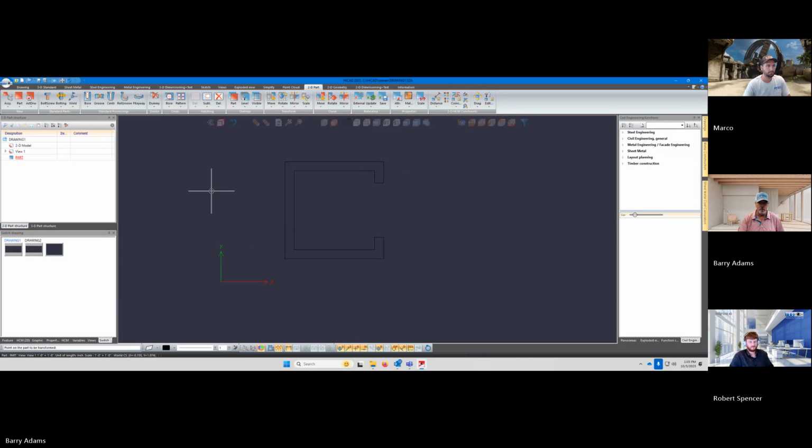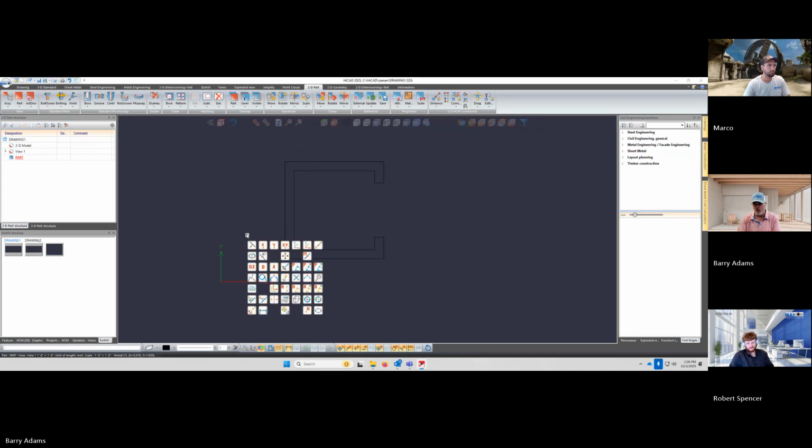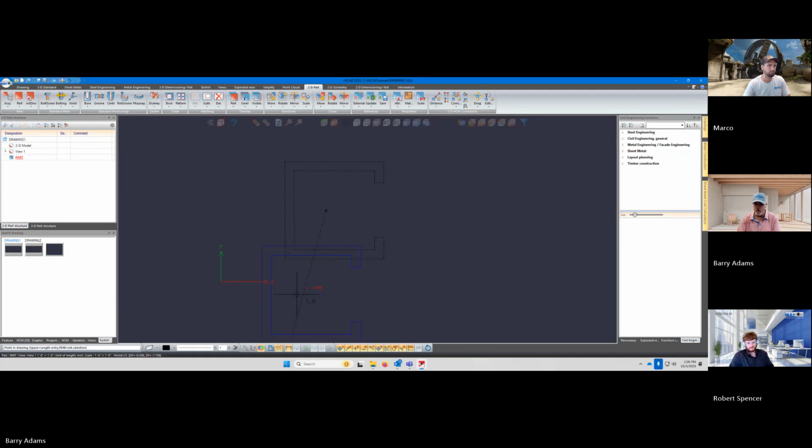Anyway, remember how to get to your point options? Enter. And you picked centroid down here. Pick that one. Now you're grabbing it by that centroid. Now in 2D, you cannot snap directly to the origin with your cursor. I find this interesting, but you can't do it with the cursor.